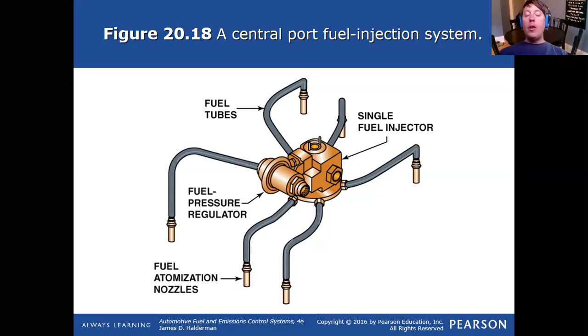And so they would hydrolock. The customer would drive the car, get to the gas station or wherever they were going, the grocery store, shut the car off, and as they walk away, all the fuel pressure is bleeding off through one of those poppet valves and dumping right into the cylinder. So when they come back out and go to crank it, they get a no start and a no crank.